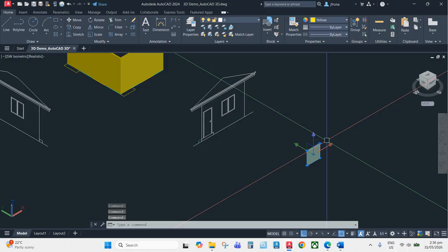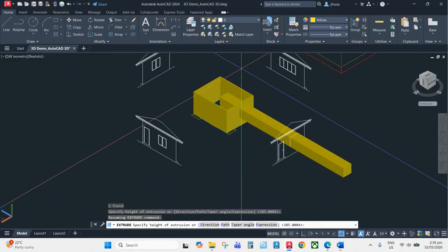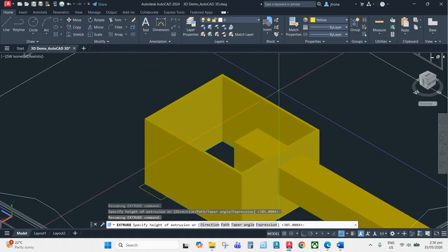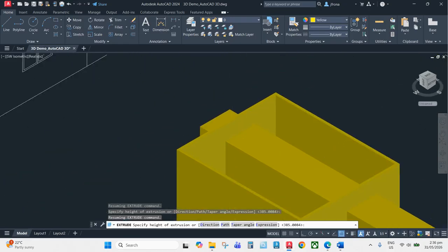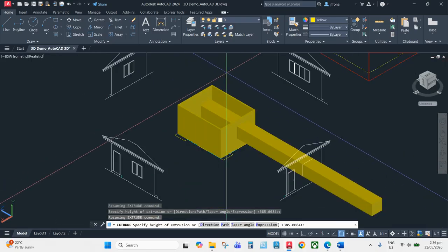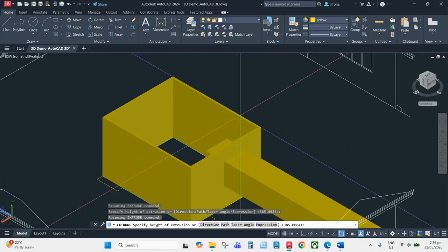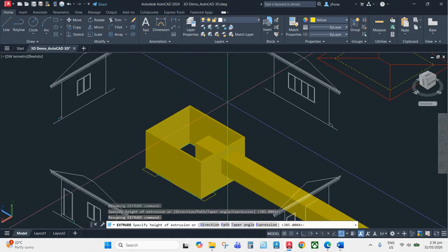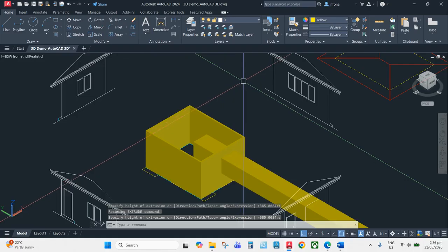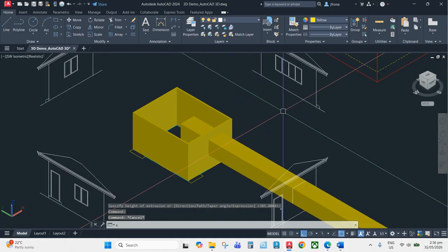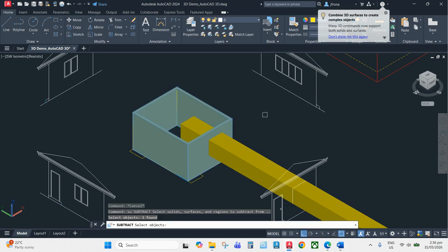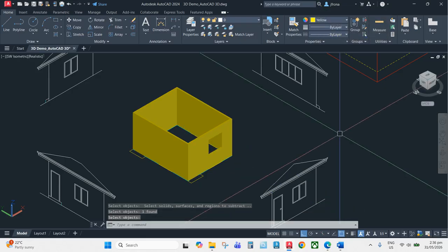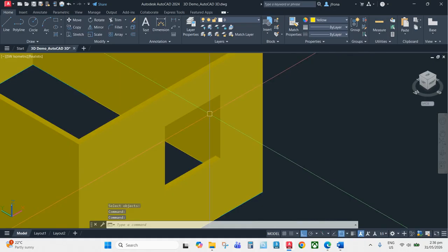That's the time you can extrude that one to the first wall. Don't make it go past the second wall, because when you subtract that, it's going to affect this wall here. So just a little past the first wall, you can see it from here, and then you select outside so it doesn't snap. Now you're ready to subtract. Select the object that you're going to retain, and select the object that you're going to subtract. So you now have an opening in your wall.